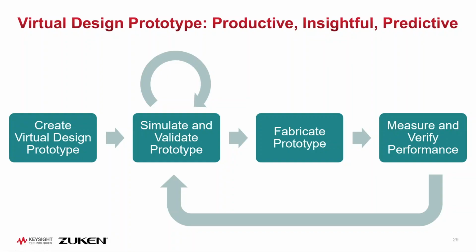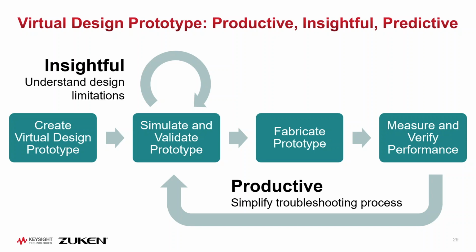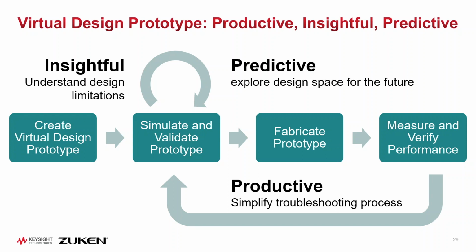Now here's a recap of the virtual design prototype, the productive, insightful, and predictive approach. It is productive because it connects the real world to the virtual world. It simplifies the troubleshooting process. Next, it is insightful because you get to understand the design limitations by doing sweeps, as one would do in the DDR5 golden channel. Finally, it is predictive because you explore the design space for the future. You get to turn on your receiver and then transmitter, set the speed to 8400, and you will see what's going to happen for that speed grade.